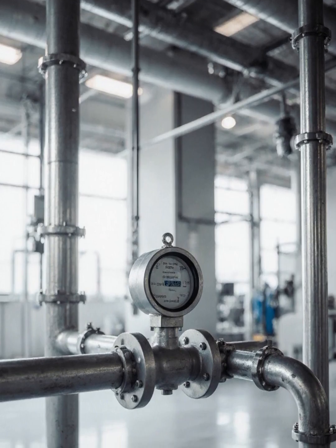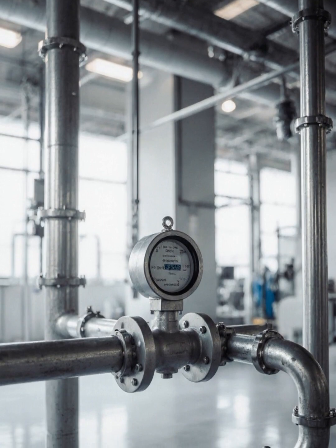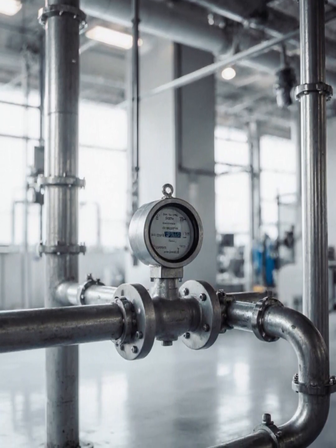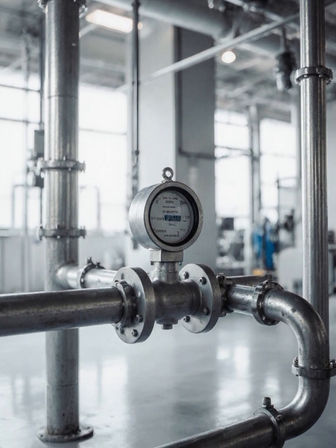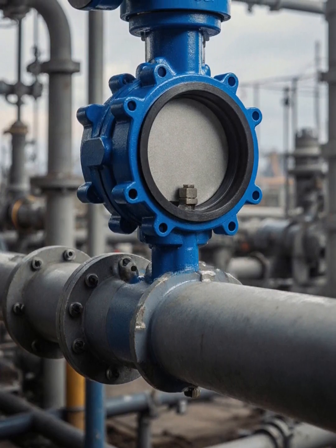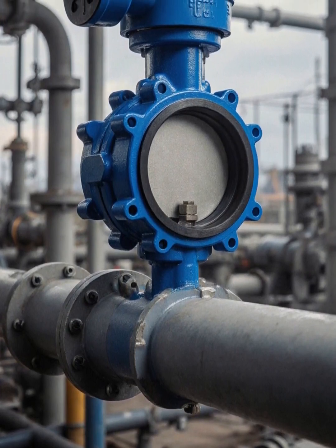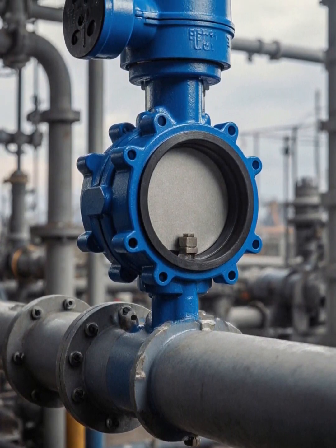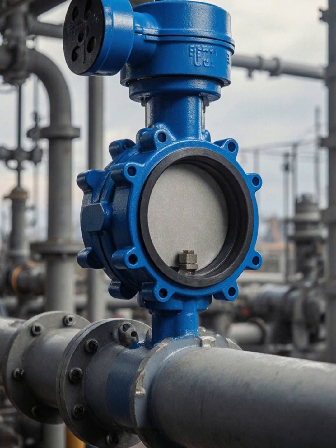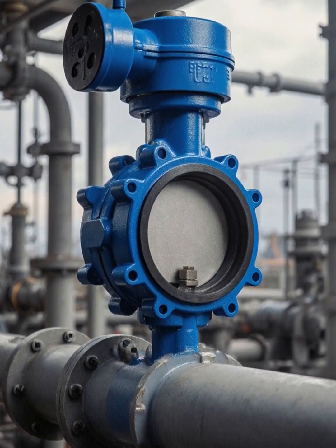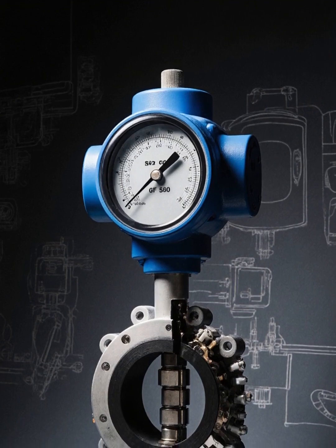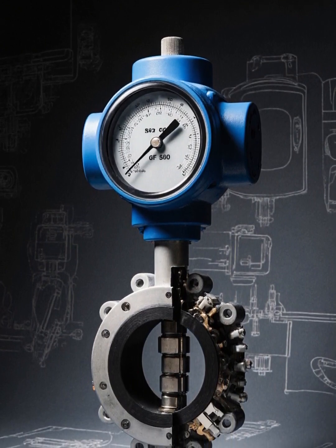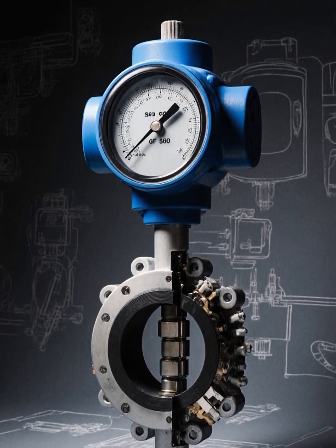A flow meter is a device that measures the rate or quantity, volume or mass, of a liquid, gas, or vapor moving through a pipe or channel, working by using different physical principles like pressure changes, velocity, or electromagnetic forces to calculate the flow, with specific mechanisms varying by type. For example, ultrasonic, magnetic, turbine, to provide data for process control, billing, or monitoring.